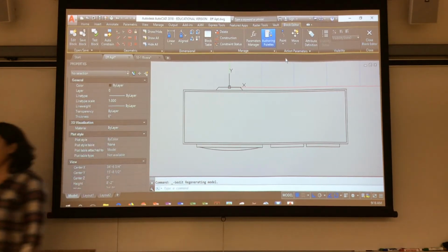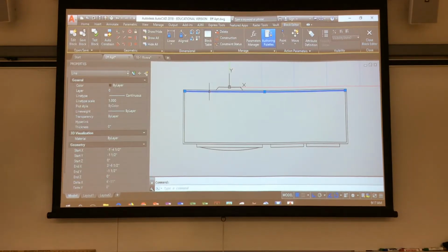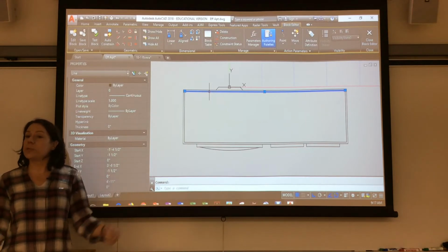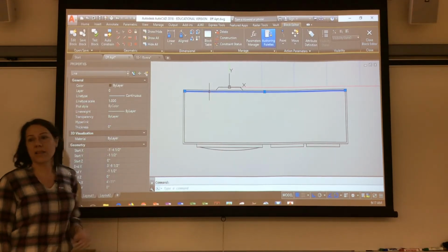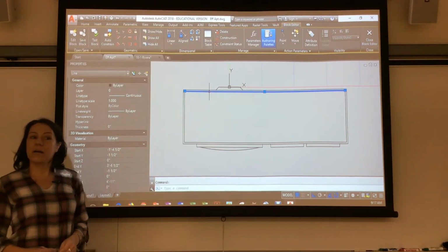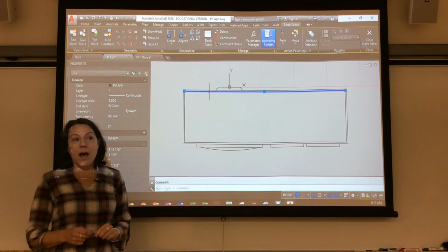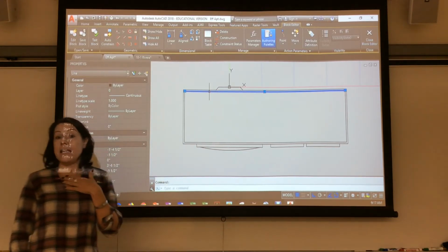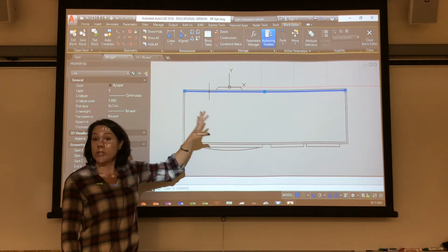Now, you've got an object, and here's the thing. All these lines are on the 0 layer. Okay? When I brought it in and exploded it, all those lines went to the 0 layer because they were put on the 0 layer here. Now, some people, I say some people, which is not me, put everything on the 0 layer in the block. I don't like to do that. If I know it's a tree, I want it on a layer that's called tree.